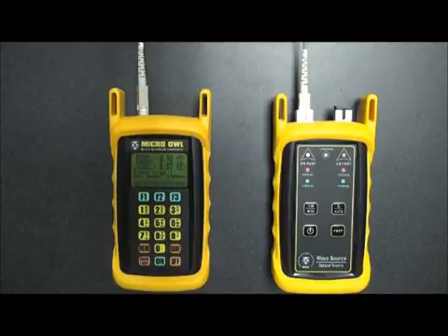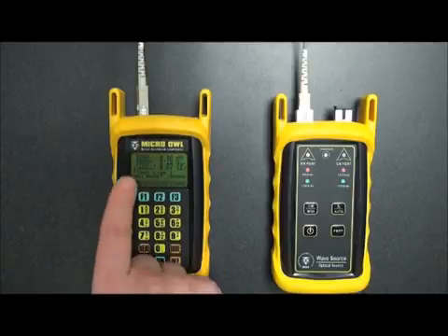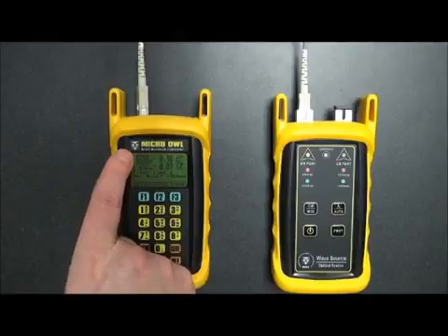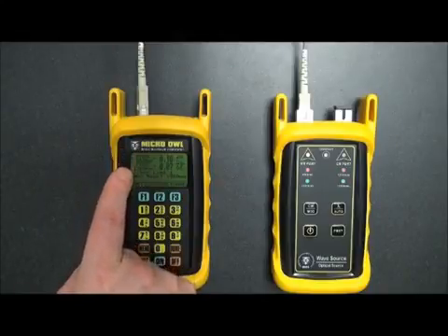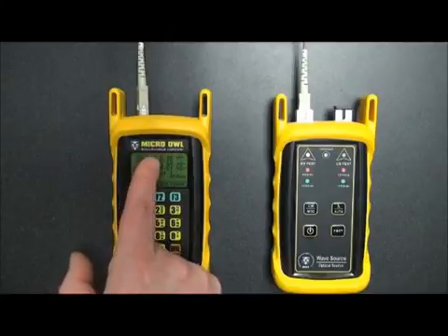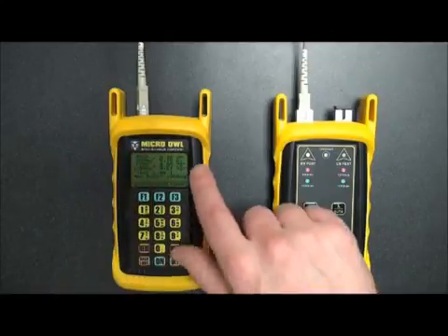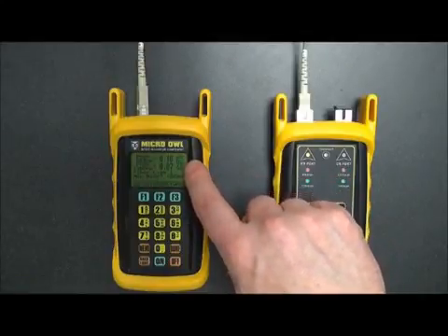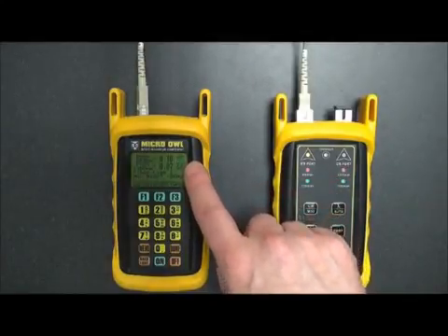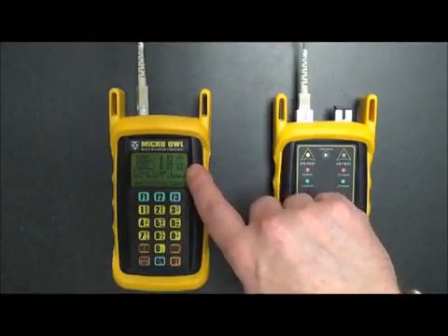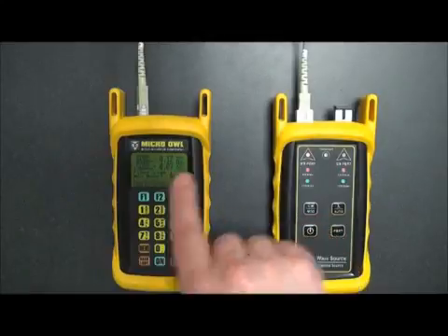Now what I'd like to do is explain a little bit about what you're seeing on the screen here. As you can see over on the left-hand side, you have your pass or fail rating, your wavelengths. And you see there's 2 different sets of data there. This big number and big numbers in the middle are your loss reading. Loss is given in dB. If you see HZ show up, that's when this flashing signal, the auto testing signal, is coming in.